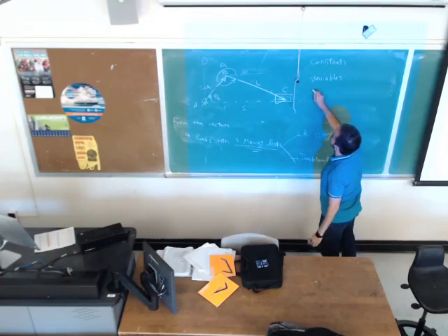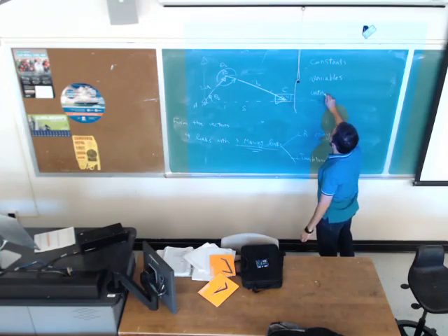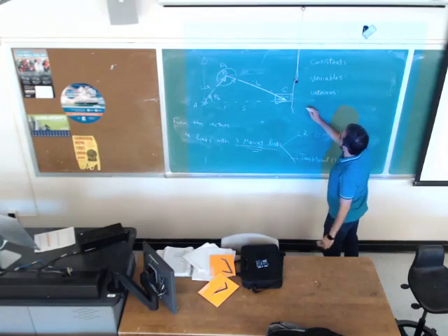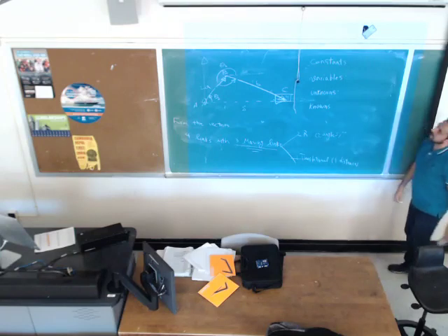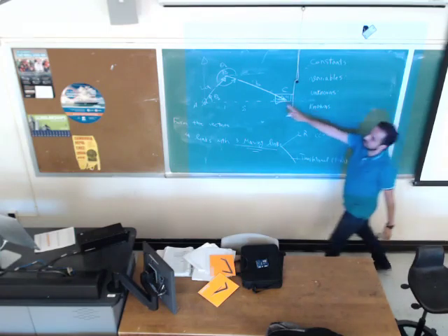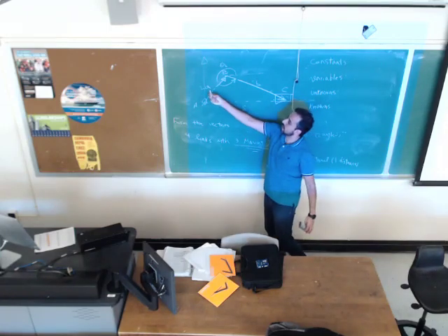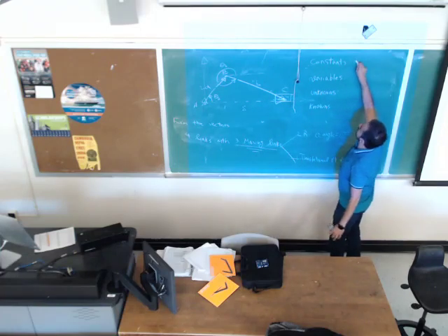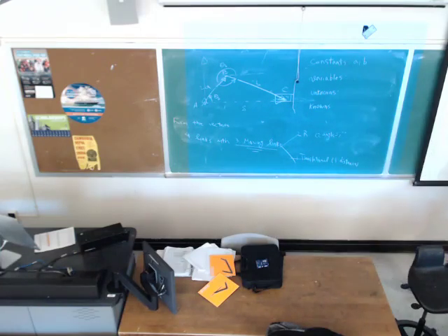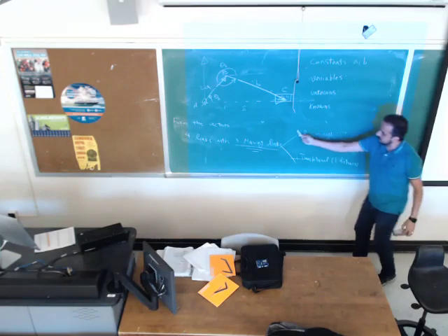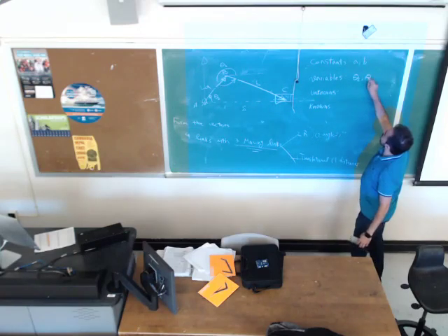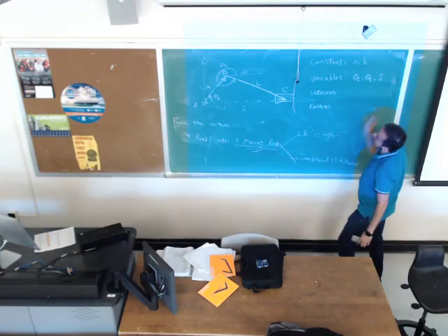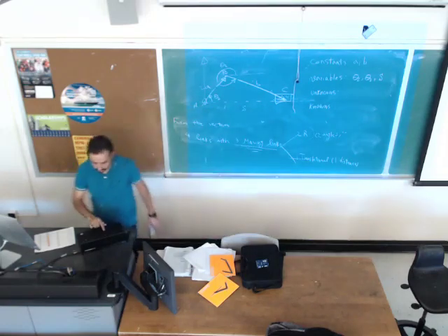You are going to repeat this for all types of mechanisms. The terms which are not changing when the mechanism is moving are lengths A and B. Variables: we have 2 angles, theta 2 and theta 3, and S, one translation, as a variable.